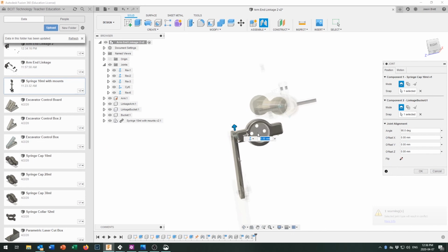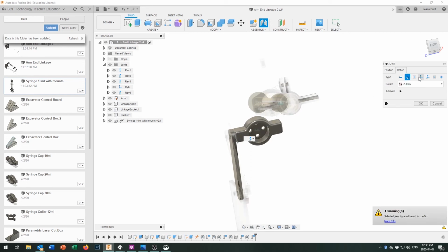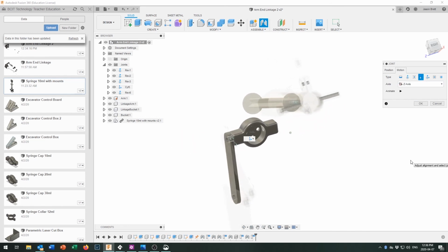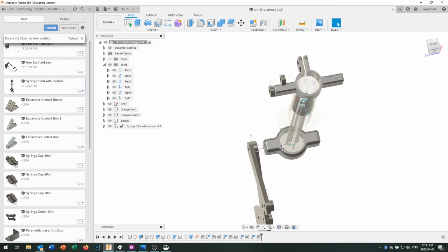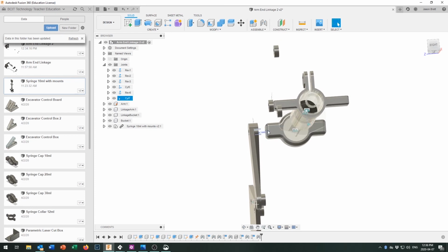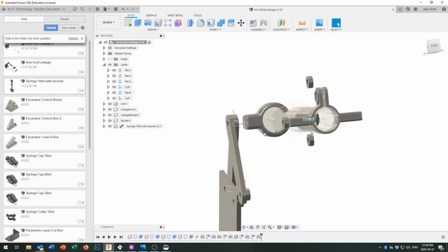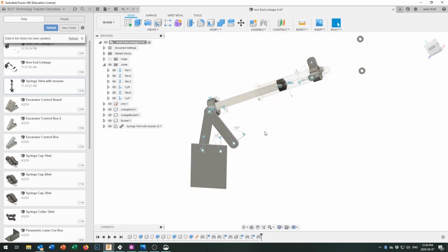And again, this one's giving us a warning saying that it'll result in a conflict. That's because there's slightly different lengths right in there. So if we come in here and tell it that the motion can be cylindrical, there we go. That warning just disappeared because now this can be spaced off a little bit right here, and we'll either have to make that part a little bit longer or we'll just run a screw right through there and life should be good.